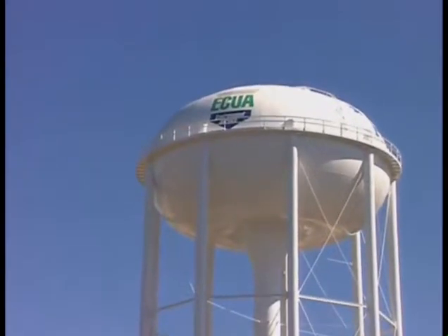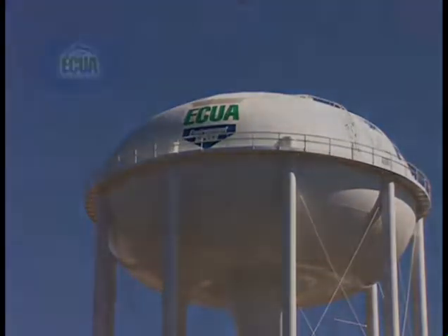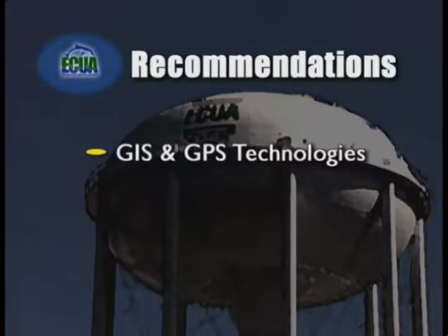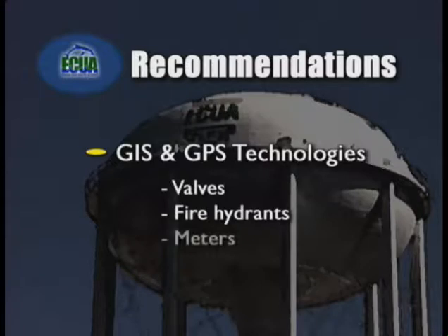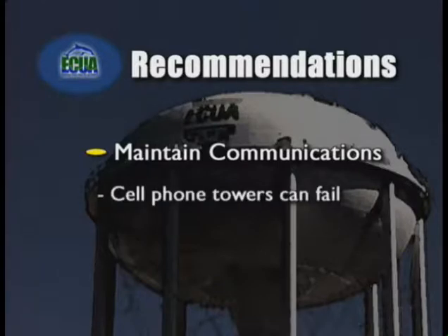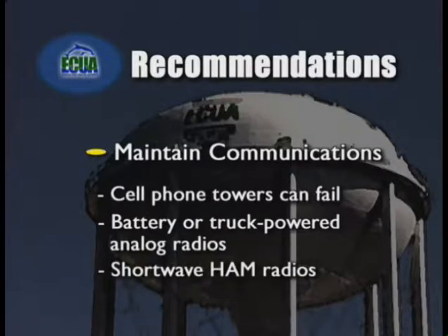The ECUA gained valuable insight in preparation and recovery efforts. Here are some of their recommendations. Using GIS and GPS technologies, mark and record infrastructure. Know where your valves, fire hydrants, and meters are located before an event. Maintaining communication is vital. Cell phone towers fail, so backup communication is essential. Consider battery or truck-powered analog radios, or even shortwave ham radios.